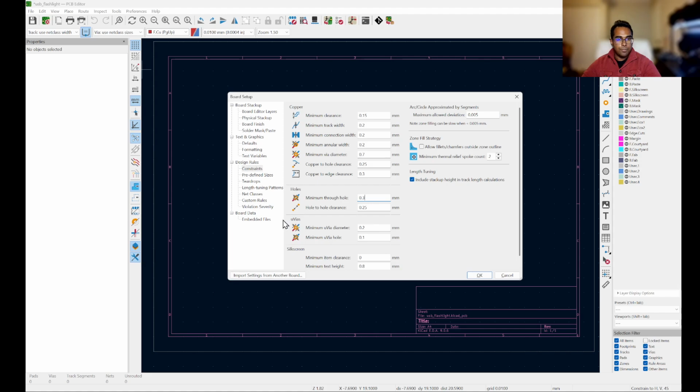And then µvias, this is a micro via. That is a whole other ball game that we're not even going to cover so much in this class, because that is a type of via used on much more advanced printed circuit boards that you're probably not going to get to for some time. Basically, micro vias are extremely tiny vias that only punch part way through the board rather than all the way through. So if you have 16 different layers, you can have vias that only connect the top 4 or something like that, rather than connecting all 16 together.